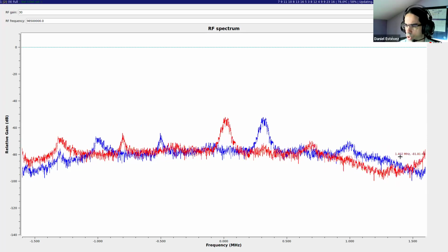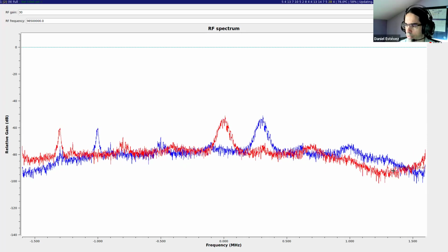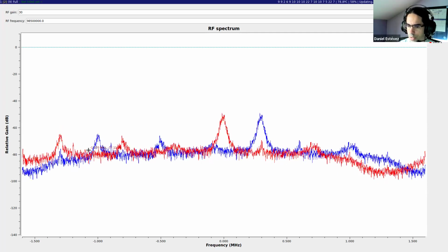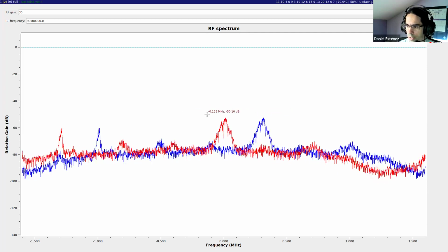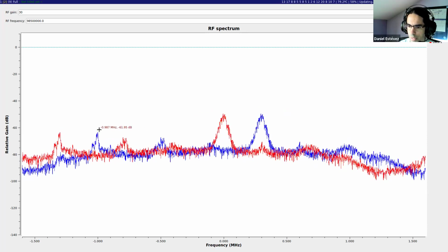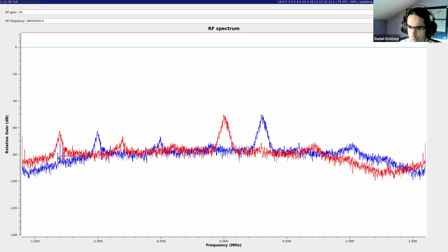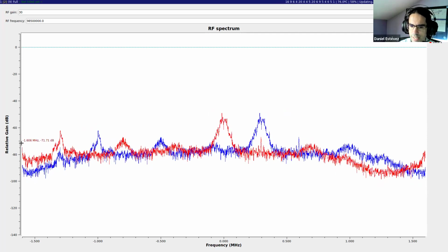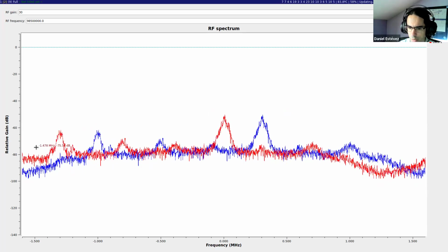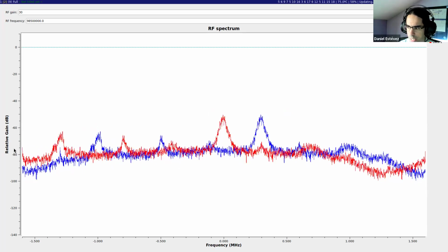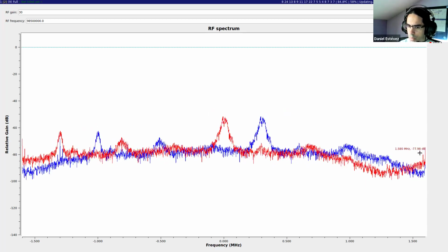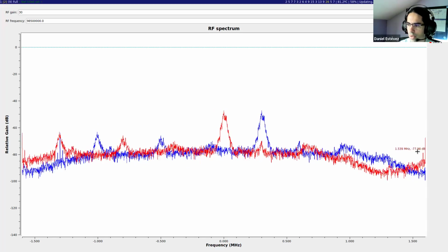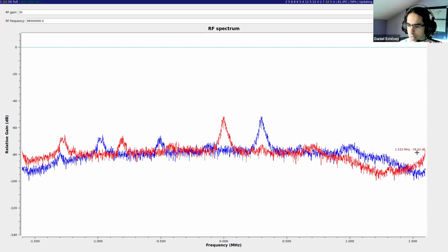And something else I should have given more emphasis before is what happens when you reach the edges. So here we are shifting everything 300 kilohertz to the left. This has gone here. But what happens, for example, with this thing? Well, it's actually here, but then when we move past the left edge, it comes back again on the right edge. So this is how aliasing works for complex sampling.